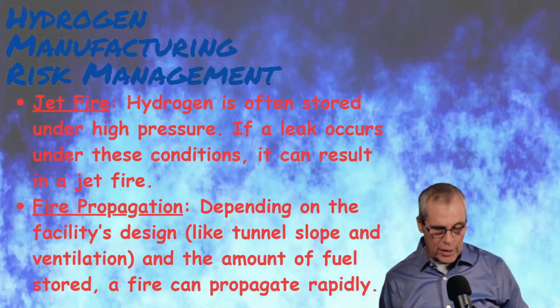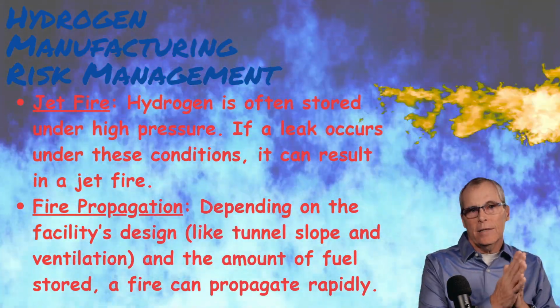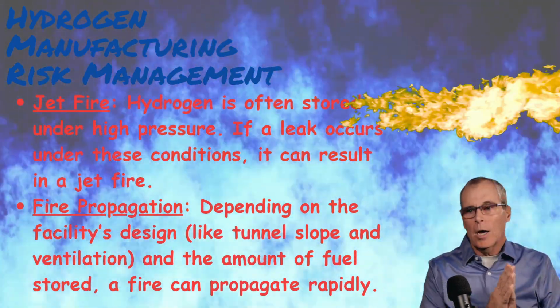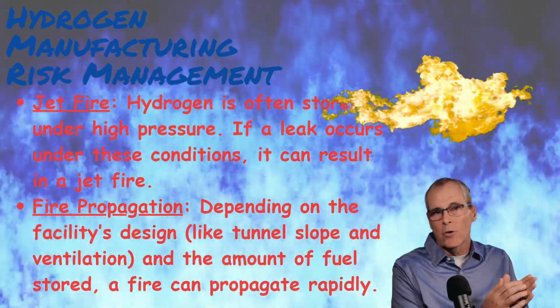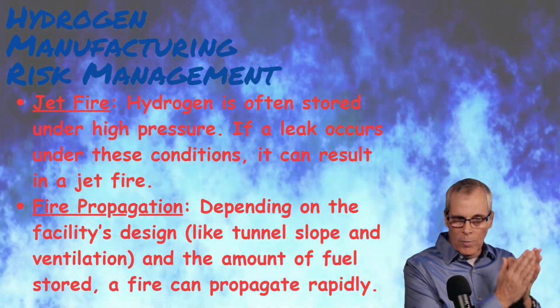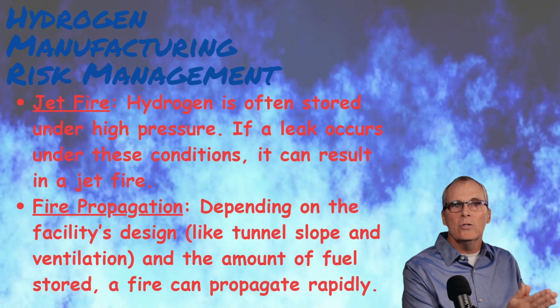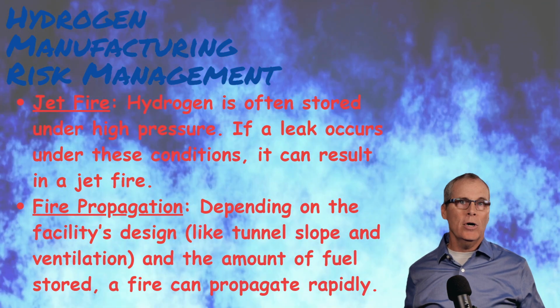Jet fires. All right, my experience with a jet fire, and this is when you have a flange or a high pressure leak that then ignites, is that the damage is very localized. Unless you've got another combustible that's going to catch on fire and spread that fire, you're pretty much going to have a lot of damage in one small place. Just like if a welder fell asleep with his torch on, it's not going anywhere.